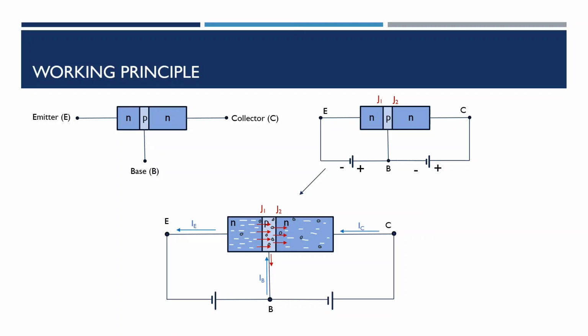Now, one other thing I ought to clear up is, why are the electrons even passing into the collector layer from the emitter layer directly? There should be a barrier at junction 2 which should stop it, right? But that's the thing. This second junction, junction 2, is reverse biased. So the injected electrons in the base terminal are the minority in this case.